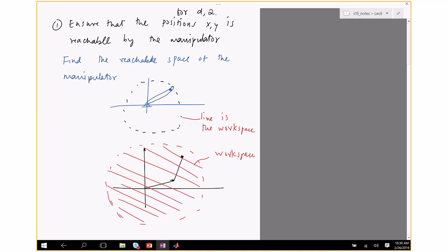However, if there are joint limits, then clearly you are constrained. For example, I have a joint limit on my elbow joint. I cannot hyperextend my joint, right? A manipulator may be able to do that, but I cannot hyperextend. So that limits how much I can move. One of your homework problems is to do the inverse kinematics, but before that, I tell you to plot the workspace when you're given joint limits.